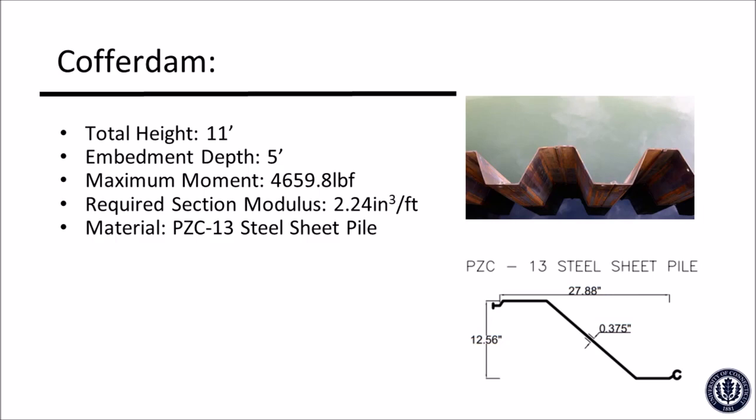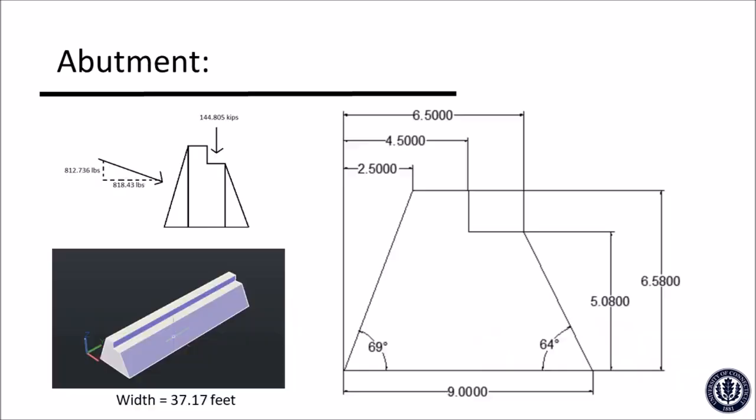To account for the 100-year flood levels, the wall will be exposed 6 feet. Given the soil conditions, the wall should fall into place relatively easy. However, misalignment is common during installation, especially considering the relatively small work area. After the main deck is removed, the cofferdam will be added to both banks, totaling 80 feet of wall on the west bank and 90 feet of wall on the east bank.